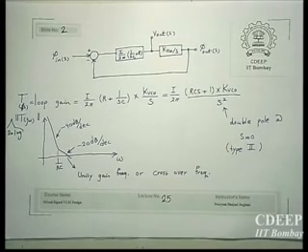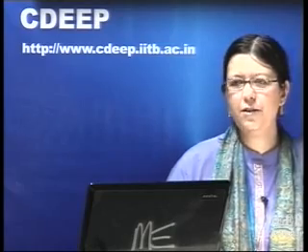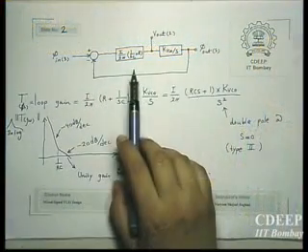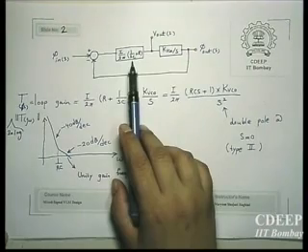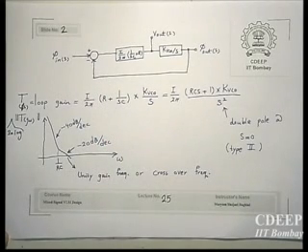And this helps to have a stable system. But an interesting point: if you look, for example, at low frequencies, you have a very high gain. It is clear from this plot. And if you look at your phase at very low frequencies, you have 180 degrees over here and 180 degrees over here, which means that you already have 360 degrees of phase inside the loop. Therefore, the loop seems to be unstable.